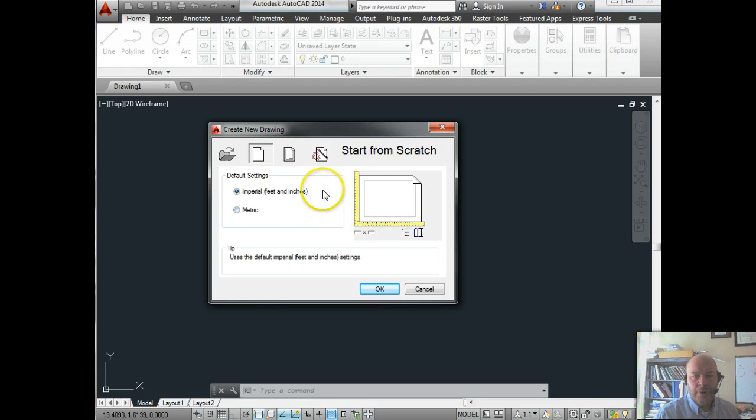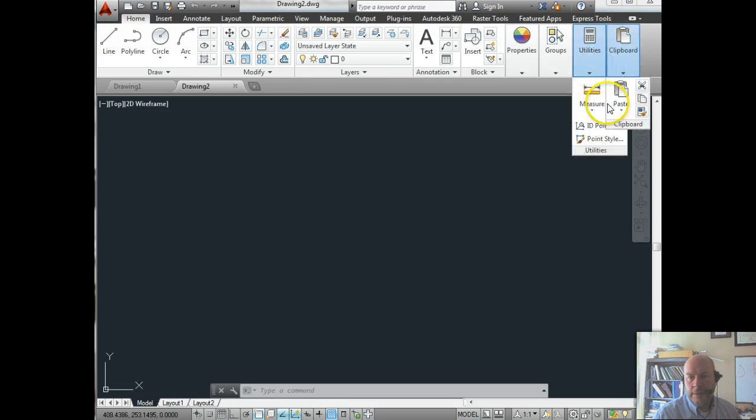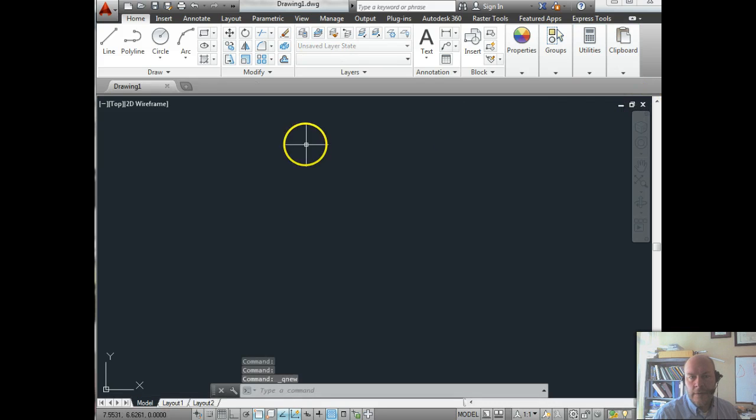And then the first thing we want to do is, we're going to use a wizard, but the first thing we want to do is tell it we're going to use metric units, instead of English units. So we're going to click on a metric drawing, so then any future elements that will be used will be metric, so we're setting the default template. Now we want to basically get rid of this, and then I'll now start a new drawing.